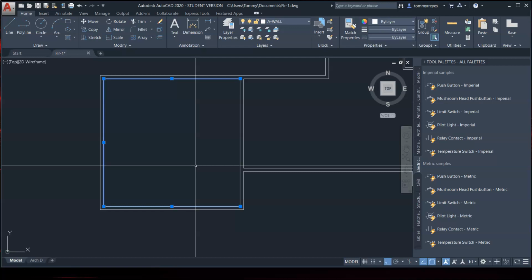Remember, if you look at figure 4-16, it clearly shows a section of the basement concrete block walls and the typical studded wall with the insulation and vapor barrier, as well as gypsum board. There's also some siding as well. So we need to adjust for that.